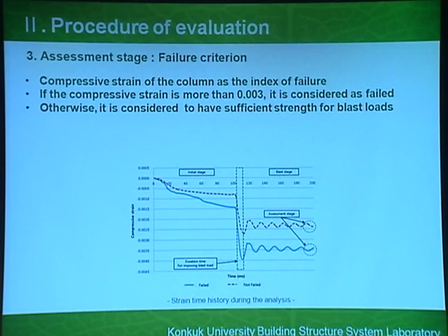That is the compression strain. So this is the failure criteria for our study. If the compression strain is more than 0.03, then we consider it failed. Otherwise, we consider the column to have residual capacity to resist further axial force or bending moment.